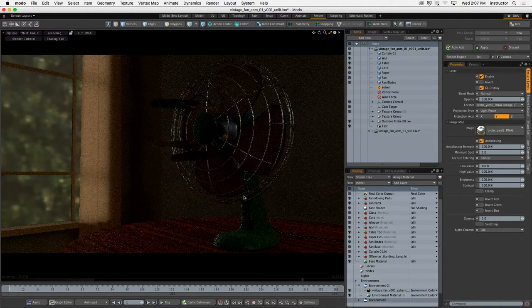There is a difference between direct lighting and indirect lighting. Direct lights are point lights, spotlights, directional lights. They are items in our item list that are physically firing off a whole bunch of light rays into our three-dimensional universe. Okay, those are direct lights, and we want to use our direct lights as much as we can because they're always going to give us a very strong result. And they're generally going to be really fast to render, okay?